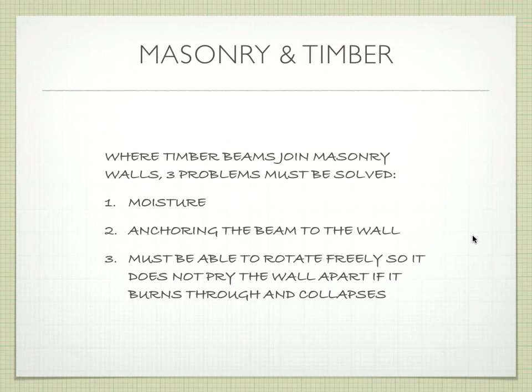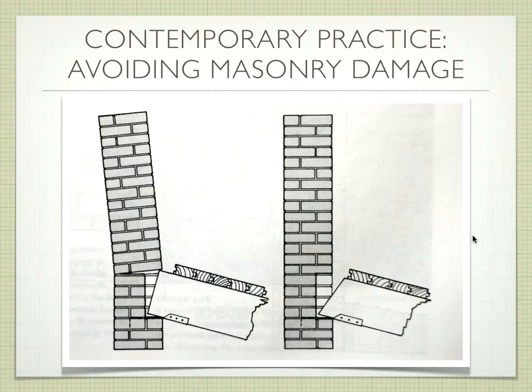Okay? And this in words sounds weird, but in illustration makes more sense. If this particular beam is resting in this wall, right, and it fits very nicely in the cavity, and something were to happen to this beam, say fire burns through it, or it fails for some other reason, when it fails, it cracks the masonry wall, and now we have the whole upper story collapsing, which is what we don't want to have happen.